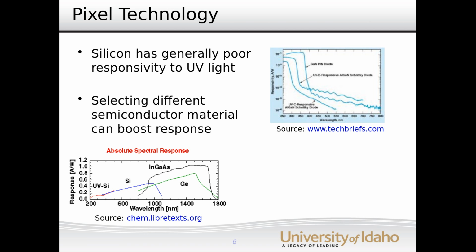Also, you're going to be restricting the wavelength range on a lot of these responses. As you can see in the top right hand graph, as you're going to some of these gallium nitride imagers, they're very, very poor in visible light, so they're not going to be useful for anything beyond the UV spectrum of light. But they are options that we can do in order to get better imaging and better response in those areas.